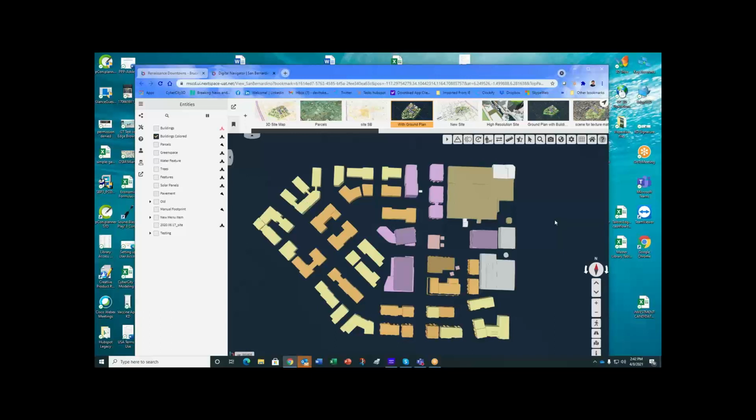I think level 1 is basic simple walls, and maybe you can have a line on each floor so we can count how many floors we have. Okay. And then the next step is basic simple windows, but get the blank walls with lines first, so we have that. Floor lines, blank walls with floor lines. Okay, that's our LOD2. That's actually very simple, because it uses a completely different workflow than what I'm using for the facade-based buildings, in that you just literally extrude them up and layer them in a floor-like manner. So that can be done pretty quickly.